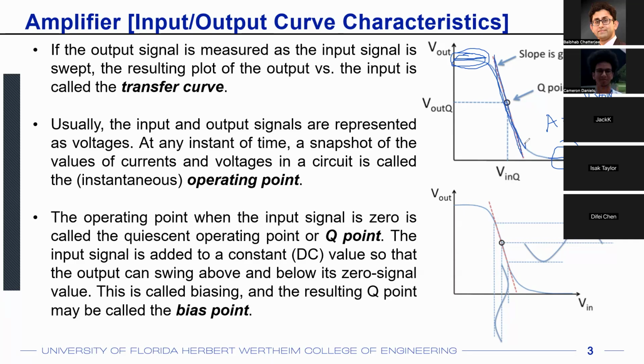And that gives you an idea. Let's sleep on that idea, and then we'll come back later in the next lecture to where your amplifier needs to be biased. It cannot amplify with the same amount of gain everywhere. If you want gain, you have to bias it at the middle of this voltage transfer curve. Okay, let's stop here. We'll discuss more in the next lecture.